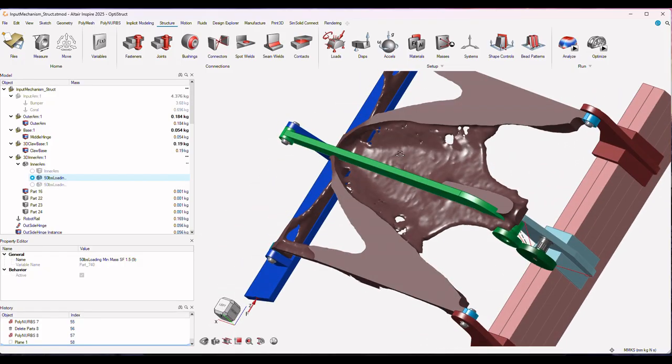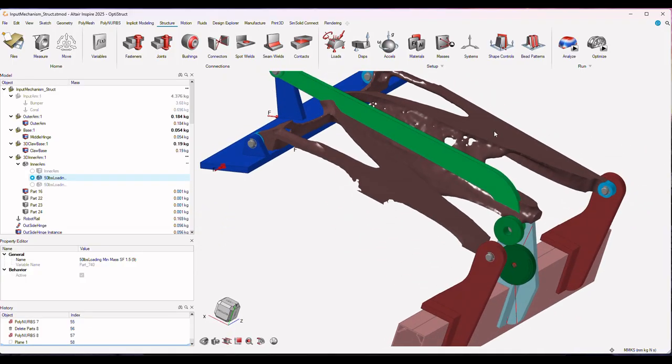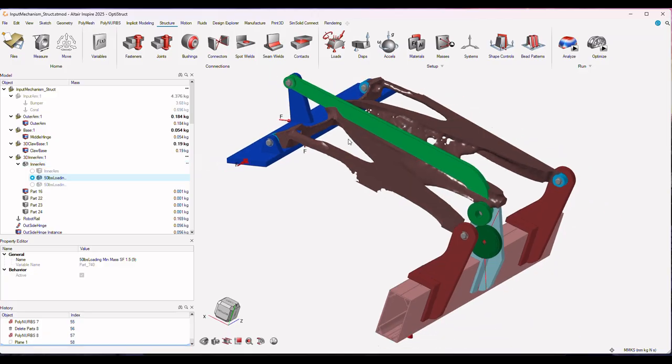Basically what I was saying is the optimization divvies this volume up into cubes. And each smaller cube has what's called a density function, but I'll call it a participation function. If you have high participation, a lot of load is going through that volume.